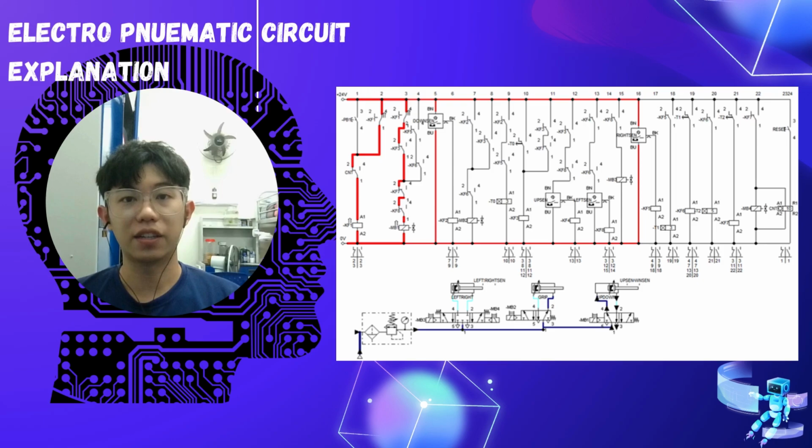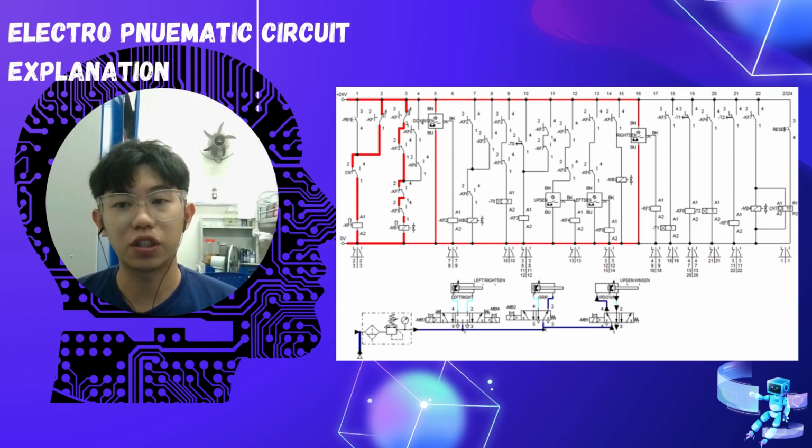So first, in the electrical circuit, when the push button PB1 is pushed, the current flows from the 24 V DC power supply and the relay KF1 is energized. The normally open contact of relay KF1 will close, leading to the energizing of valve solenoid MB1. In the pneumatic circuit, a magnetic field is produced in coil MB1. Then it activates the left switching position.